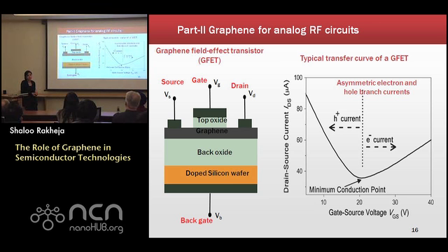So you can see, it's sort of an optimistic way of looking at it. But even in this optimistic view, we see that graphene does not do a very good job at advanced nodes. If you were to take graphene on SiO2, for instance, it would be much worse. Or if the edge roughness was more, it would have a much higher latency than copper. So these are optimistic, yet we have incorporated some of the realistic effects that matter to us.